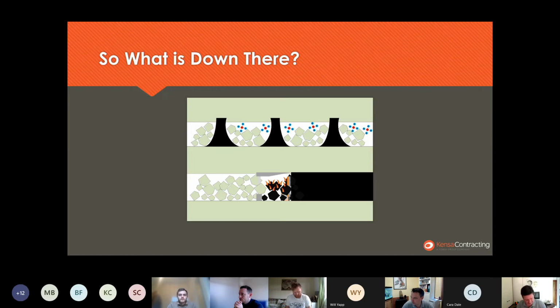Cool. Any questions? Chris, yeah, while we're on that, how do we drill through mines, and do they require casing? They sometimes require casing. Many times, though, they can just go through them as if it's a void, like any other void in the ground, and they just go out the other side. It can make completion of the borehole, so the grouting that we talked about in earlier sessions, sealing that borehole up, a bit more challenging. And we sometimes have conversations with the drillers to say, do we use gravel to fill that hole up rather than grout? And there are procedures around that.